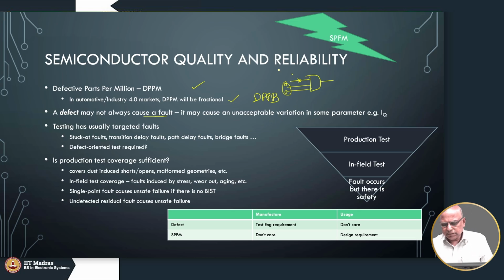As a result, that defect never got uncovered during the normal mode. I am talking about normal mode. In the test mode, we will of course apply 1 and we will do that. But I am saying, if you are worried about reliability, etc., during normal mode of operation, maybe this fault remains hidden. It's called a dormant fault.